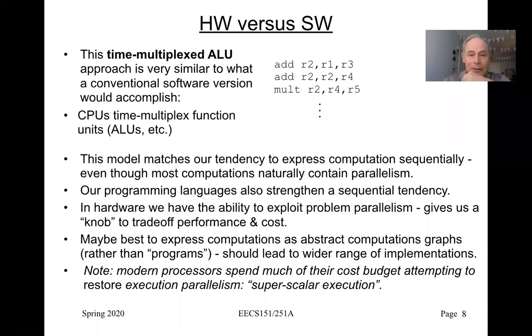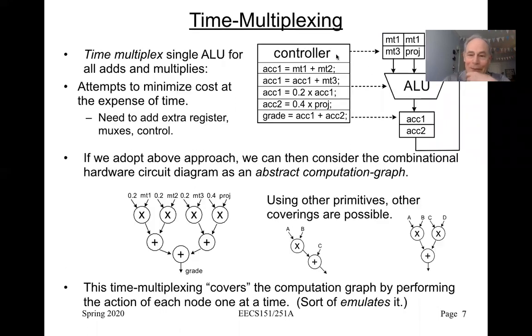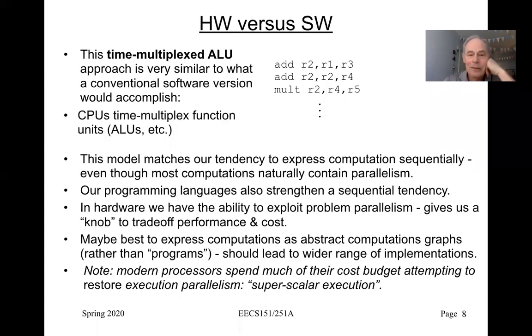So if we look at this solution here, it reminds you of a software solution. This is like a little program that we're executing here. That's the action of the controller. So it gets us to think about the differences between hardware and software. This time multiplexed ALU approach is very similar to what you would see if you wrote a program for a processor. If you took our RISC-V processor, you could implement the same function by doing some adds and multiplies, and it would initiate one operation per cycle.